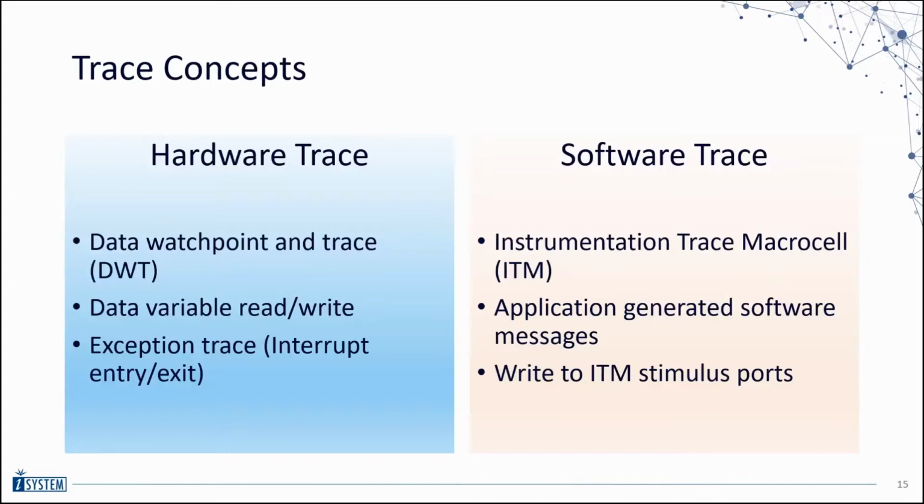The important question is, how do we gather the data? In general, either by software trace or hardware trace. I'm not going very deep into these two concepts, but in the context of hardware trace, I talk about DWT. The DWT module has hardware comparators, which can not only detect data of interest, but also capture the data from the CPU. Later, it is forwarded to ITM, where trace messages are formed and sent to the TPIU unit.